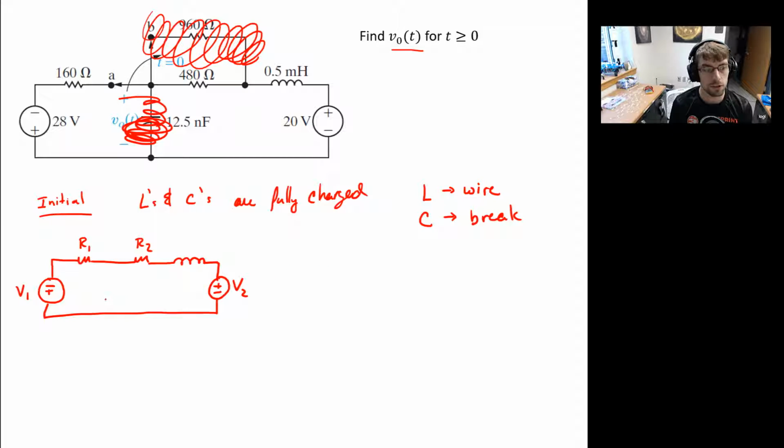And so what we can do is apply, probably KVL is the easiest way to go. Let's just apply KVL. Okay. And if I'm going to walk counterclockwise around this loop, what we end up having is two potential drops across the resistors and two potential jumps across the batteries, or the voltage supplies, I should say. V1 plus V2 equals. Now I'll go ahead and use an uppercase I, because we're talking about when these things are fully charged, so the currents won't be varying at all.